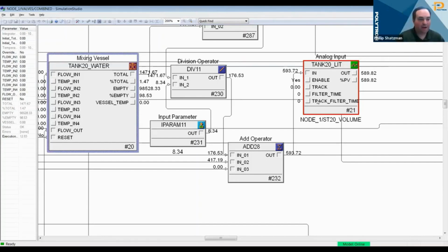Yeah, and if I can add on to that, essentially, all you need to create this model is the P&ID diagram showing the flow of the system and what objects you have in there. At that point, you can create the model, and it can actually even be created before the programming is completed. Exactly. That's something that we tend to do, is create both the model and the program at the same time, so that once the program is done and ready to be tested out, we have a system ready for it. Right.